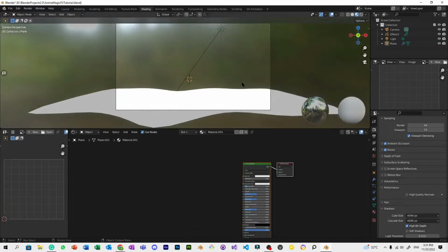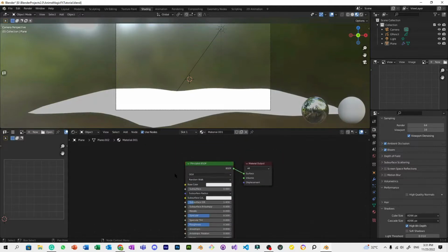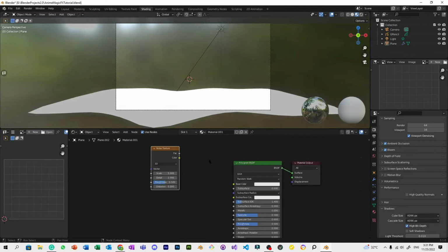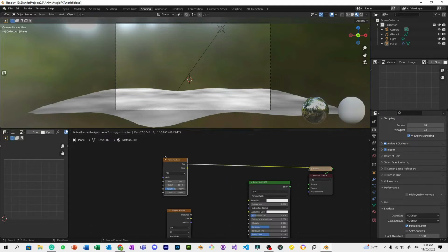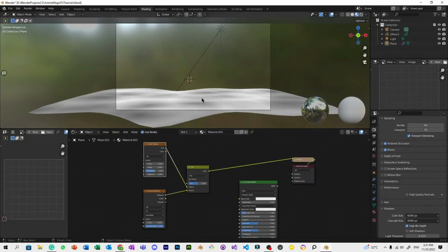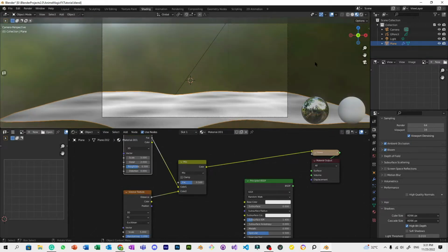Now next is the material shade. To do this, it's very simple. All you need to do is principled BSDF, material output, put a noise texture, then Control Shift right click to see the preview. Voronoi texture, going to mix these two. Then as you can see from the main scene, I'm just recreating this once again so you can see the